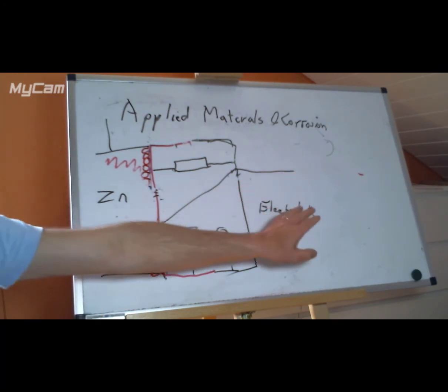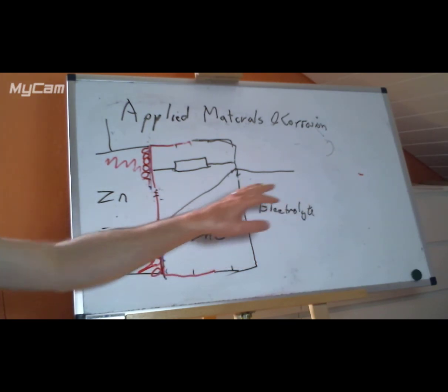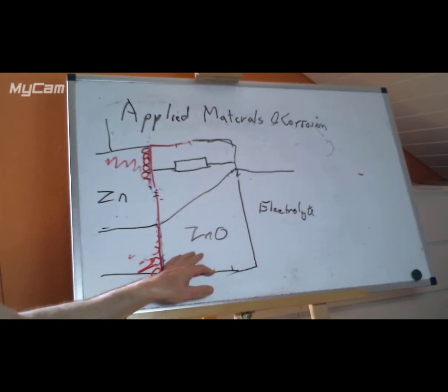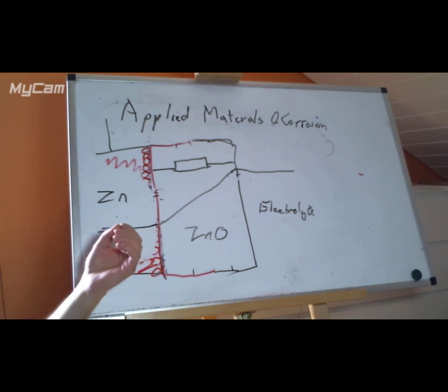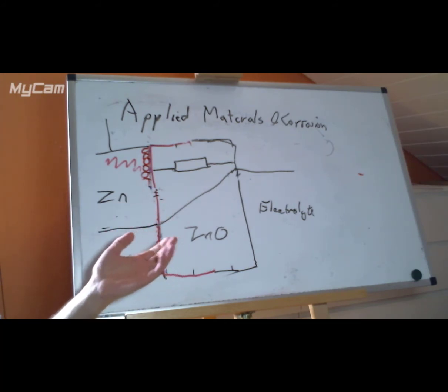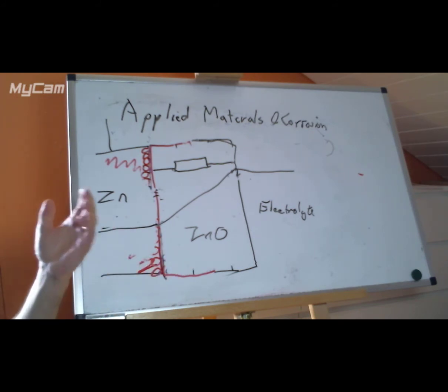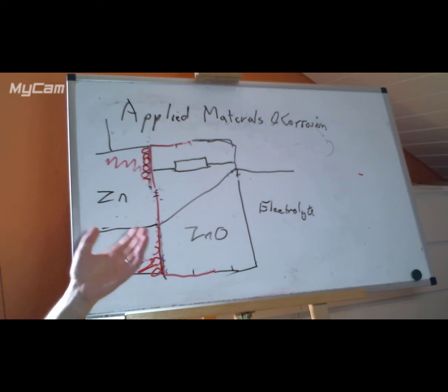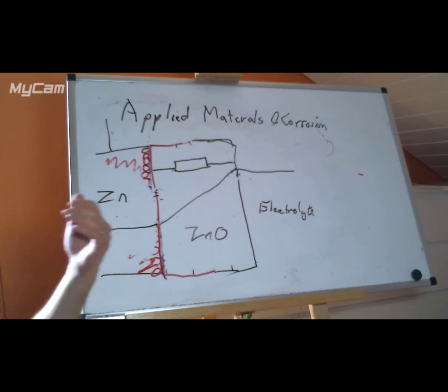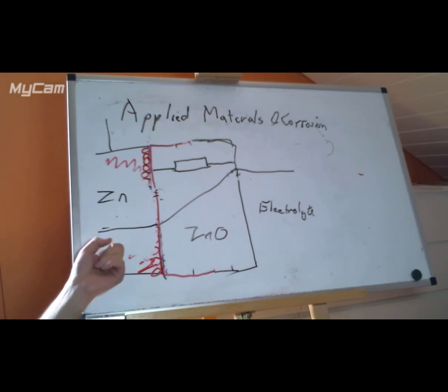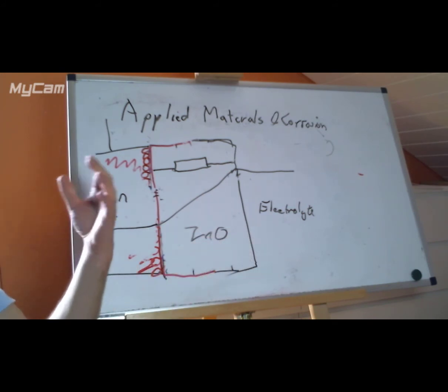It depends on the relative conductivity of the electrolyte and that of the oxide layer. So on a stainless steel surface, for example, where the oxide layer is very thin and reasonably conductive, we don't see very much effect. And on an aluminium surface, the aluminium oxide layer is reasonably thick, although it's not that thick, but it's quite resistive. Then we see a big difference between the electrical potential of the metal and that of the electrolyte.